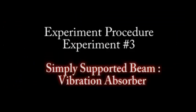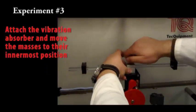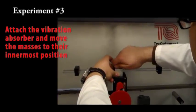Experiment 3. Simply supported beam vibration absorber. Anti-resonance. Disconnect the dashpot damper from the beam. Fit the vibration absorber here.